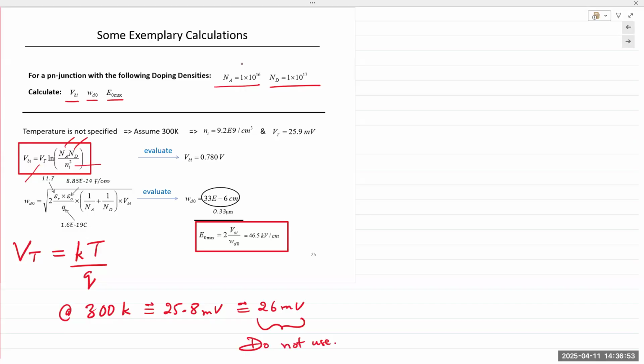Okay, calculate your own. This is a very common term that you will come across over and over again. So kT over q: k is Boltzmann's constant, q is one unit charge, T is temperature in Kelvin. Typically, I like to go to 3 or 4 decimal places, so 25.7999, at least 4 decimal places. You can use 2 or 3, that's fine. It turns out approximately 25.8.